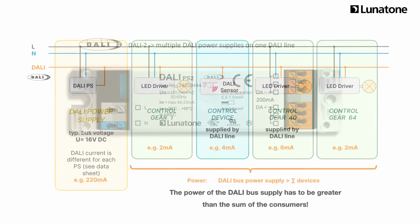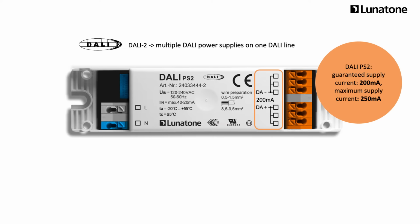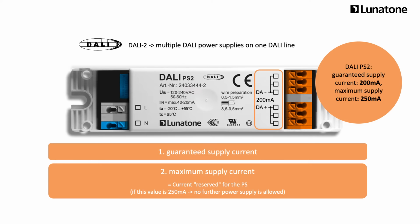According to the DALI-2 specification, it is also possible to connect multiple DALI power supplies to one line. For this purpose, the terminals on the new DALI-2 power supplies are marked with plus and minus. In the DALI power supply datasheet, you will find two values that will show whether a device is suitable for this: the guaranteed supply current and the maximum supply current.